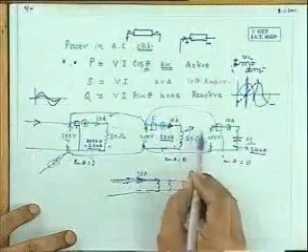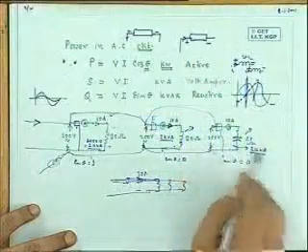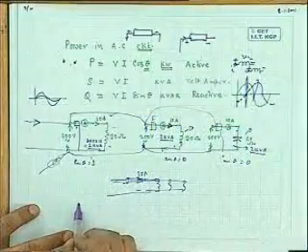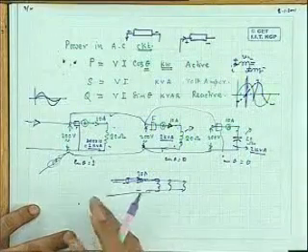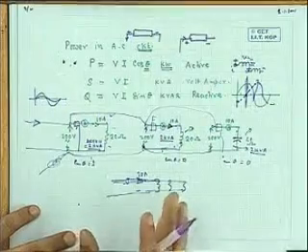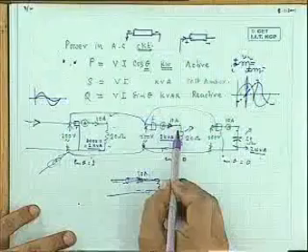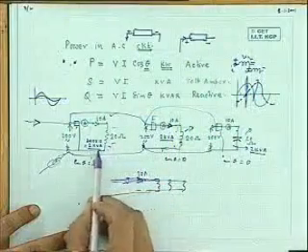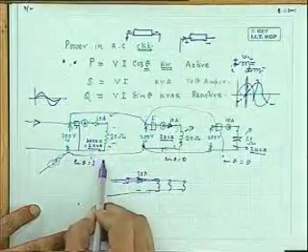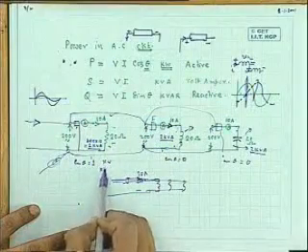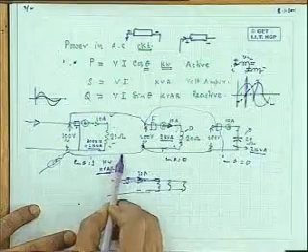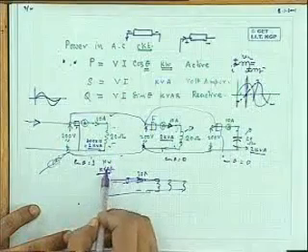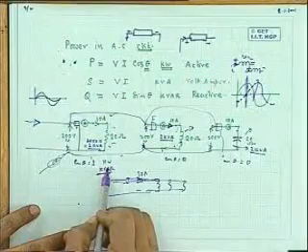Is it clear? Therefore, to avoid such imaginary consumers, the power supply authority will specify that you have to take power at a certain power factor, otherwise you will be penalized. Sometimes the power system authority calculates the real power, how many kilowatts he is drawing, and also how many kVAR, reactive power, he is drawing, and then he will be billed.